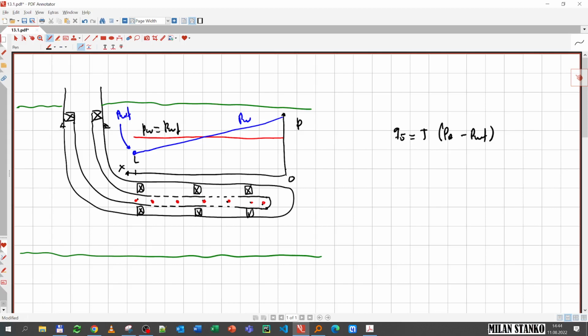Well, we know the derivative of pressure, how the pressure is changing along the distance, the pressure along the wellbore, is actually given by density of oil, if I'm assuming it's only oil flowing here, times friction factor, divided by the diameter, times velocity squared divided by 2. We're assuming that there is no change in elevation. It's a perfectly horizontal wellbore, and also the liquid is relatively incompressible, because the change in the kinetic energy term is not much from toe to heel. So I'm neglecting that part and considering only the friction part.